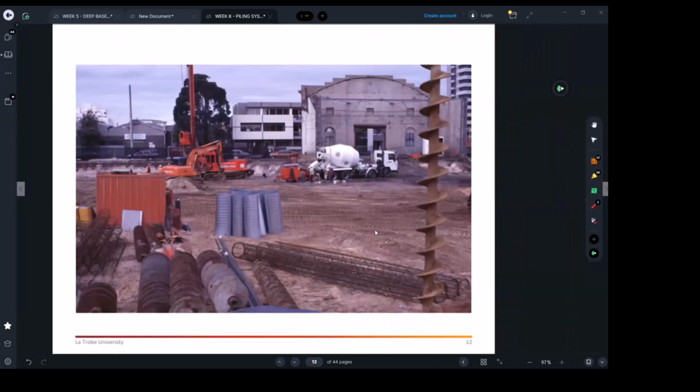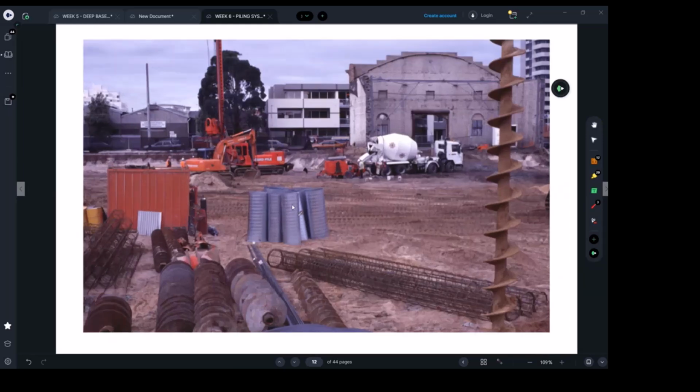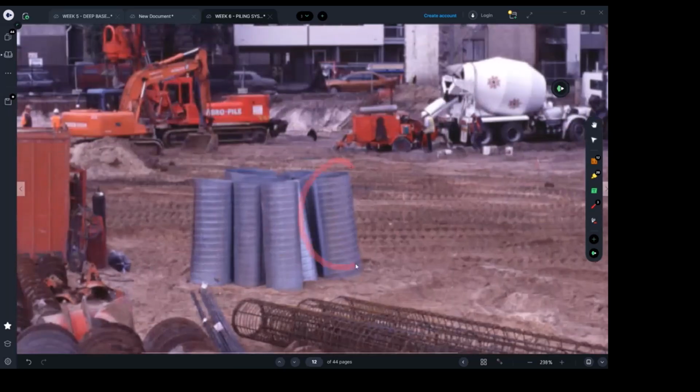Here we go. So sometimes we use, in order to place those, so why are we using those? I was telling you, if you have a 1 meter fill, and let's say we need to stabilize it temporarily, we use the drilling bucket to drill, say, 900 diameter through that 1 meter.